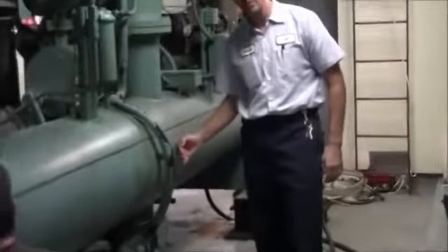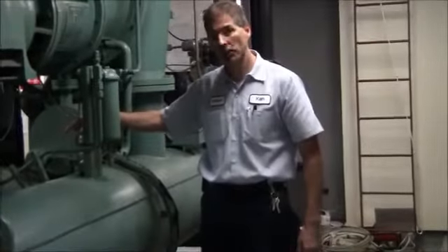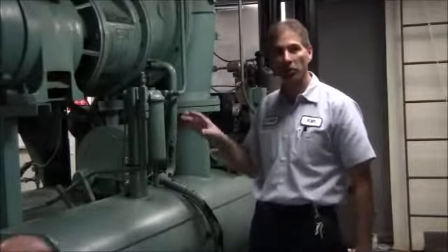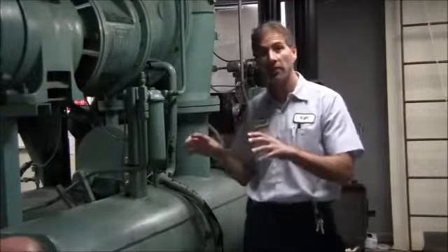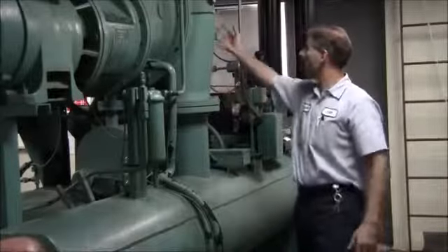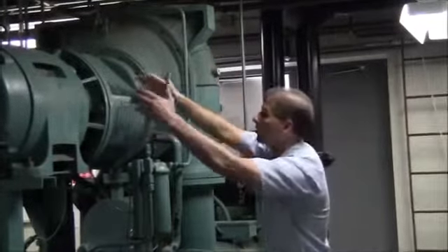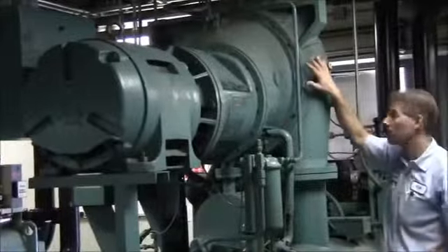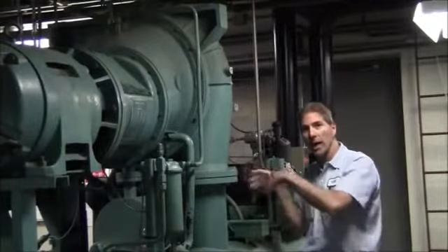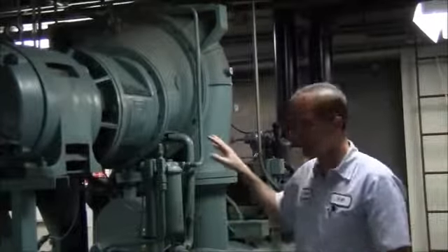Then it goes through a metering device, where at that point it enters into the evaporator section, where the liquid refrigerant will boil off due to the chilled water passing through it. The chilled water will give up its heat to the refrigerant, boiling it off and turning it back into a vapor, where it travels to the inlet side of the impellers on this large compressor right here. Here's the motor. This is a coupling in between, which is driving the impeller. There's a gearbox over here which operates a set of vanes to allow the flow of refrigerant to adjust to the load. So that's how the chiller kind of operates.